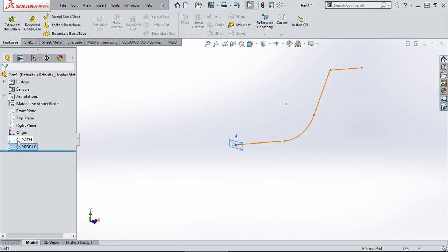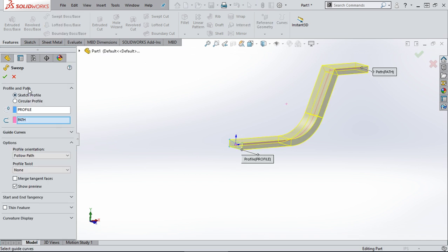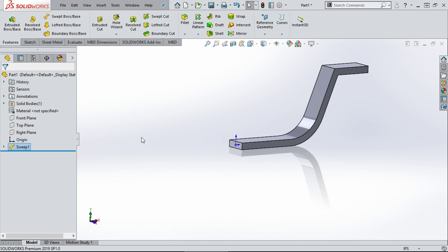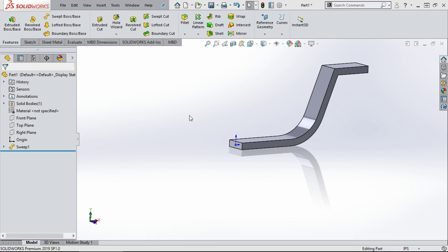So let's say I switch the order of that. I pick the lower one first this time. You can see SolidWorks still gets it. So multi-selecting as a pre-selection tool can also be a great time saver when it comes to working with the Control key. It's another great way to save some time. Just get in there and hold the Control key when you're doing your multi-selection.